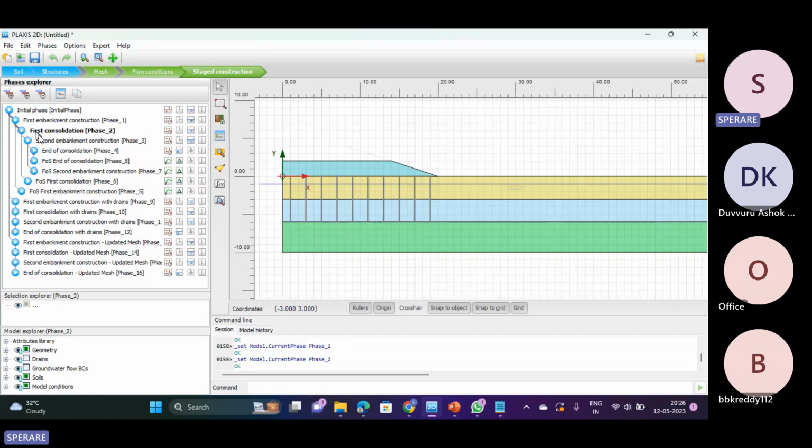After consolidation, the strength has maybe increased. So at that point in time, I identify what the factor of safety is. Next, again I'm backfilling. Over stage one, if I fill the backfill of the second stage, then in this case I identify the factor of safety. Next, again I'm going for the final consolidation, and after the final consolidation, again I'm doing the factor of safety analysis. Now, from this point to this point, do you have a clear idea of what we are doing?